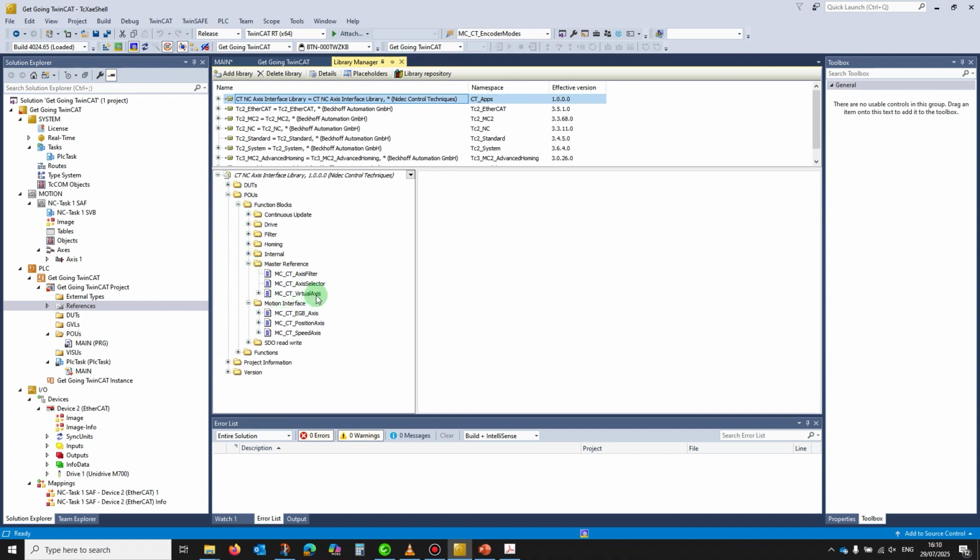So you've got a virtual axis. If you're going to do something like an electronic line shaft from a virtual reference, we've given you a block to be able to control that. We've given you one for EGB, which essentially is dressing up the MC gear in function block to do an electronic gear lock to another axis, to another encoder, or to a virtual axis. We've got the position axis. This is basically jogging, stopping, and various types of position reference: absolute, relative, modulo, all of the different options. And last of all, a more simple speed axis.